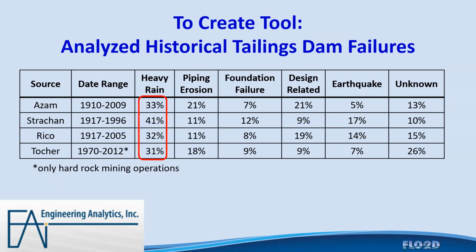And with the data provided by the user in the tool, which I'll show you in a minute, for the different failure modes, for example the hydrologic failure, we ended up calculating different processes behind the event trees that I'm going to show you, like the overtopping or the potential blockage of the spillway.